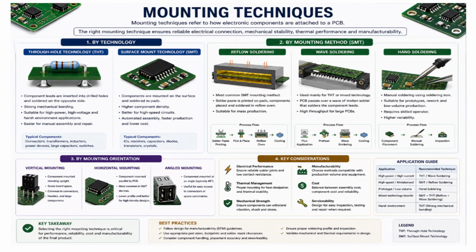Now mounting techniques. So what are the major mounting techniques? Mounting techniques refer to how electronic components are attached to the PCB, right? From the technology point of view, you have through-hole technology, called THT, then surface mount technology, which is also one of the important ones.